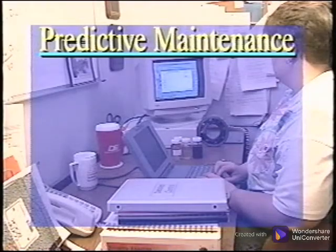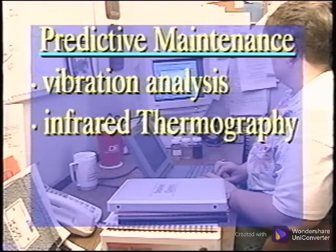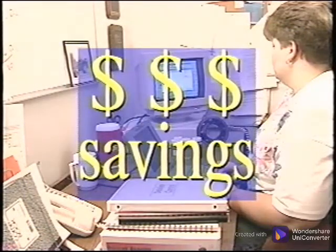This predictive maintenance philosophy is actually much more involved than condition monitoring and uses many technologies such as vibration analysis, infrared thermography, motor current analysis, and oil analysis to determine the present condition and predict the future for the machine. Predictive maintenance programs have proven savings of millions of dollars in maintenance costs.